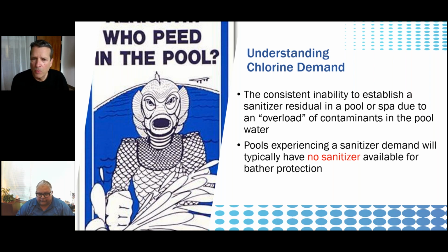All right, so back to root cause. The first reason why you wouldn't hold chlorine in a saltwater pool is chlorine demand. And that's simply you have too much garbage in the water. And so all the chlorine that you're making is getting burnt up very quickly. And a lot of times, the symptom of that is you have no free chlorine residual. A lot of times what people assume is when they stop holding chlorine in a saltwater pool, their first assumption is the cell stopped working.